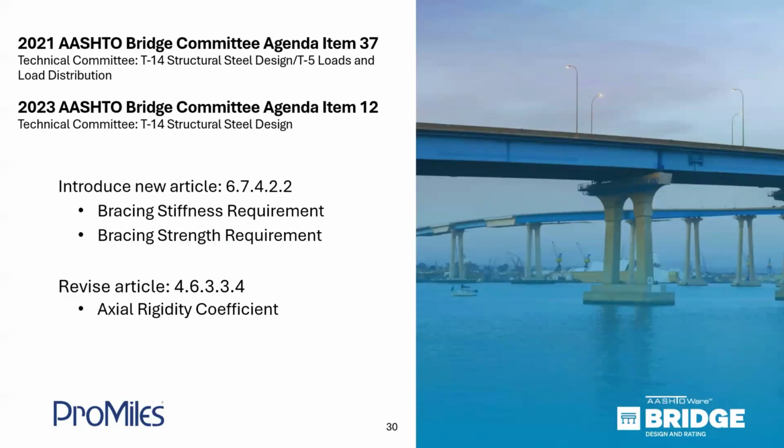These new requirements for cross-frames are the result of two ballot items. A 2021 item introduced the new stability article, which is 6.7.4.2.2, and provided a revision for 4.6.3.4 or 3.3.4 to consider a stiffness reduction coefficient. And then in 2023, there's a modification to reduce the required strength and stiffness for cross frames when certain conditions are satisfied.